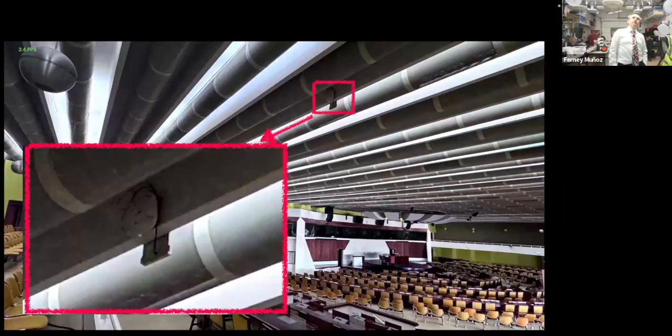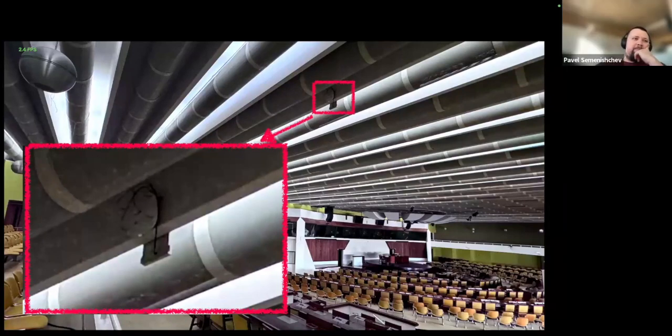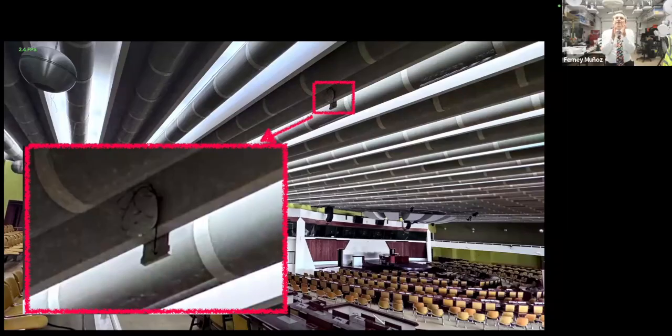Because I was doing a survey and they said, yeah, Wi-Fi here is really bad. They have a directional antenna, you're right, and they're aiming at the roof. Where do I need the waves? Down where people are sitting, down here. The antenna is aiming at the roof. So the semi-directional antenna is covering what I don't want to cover.